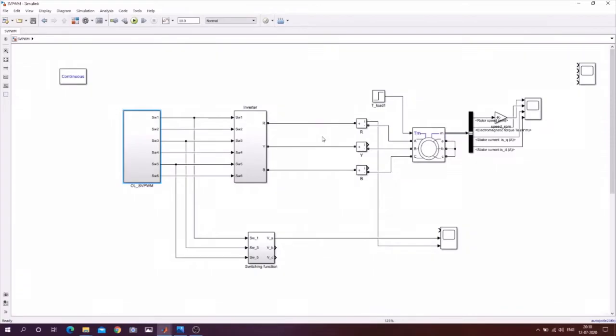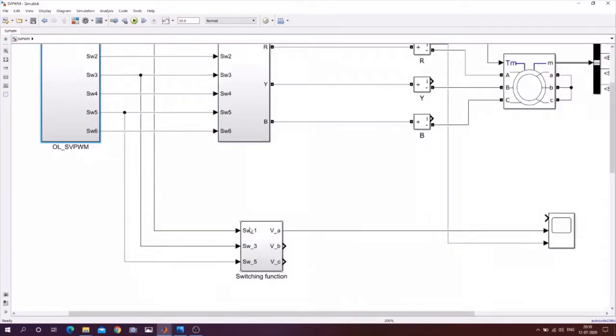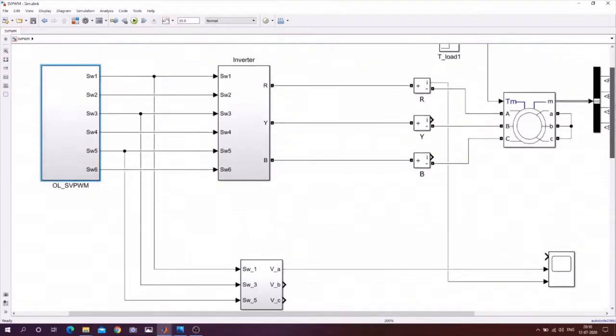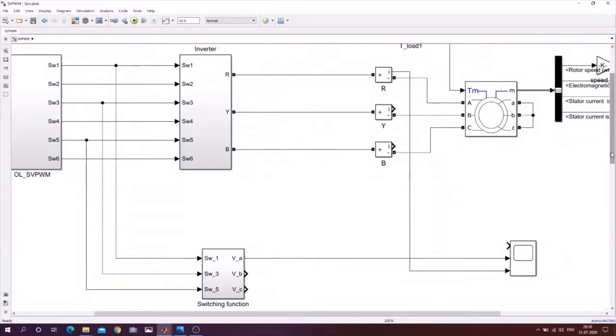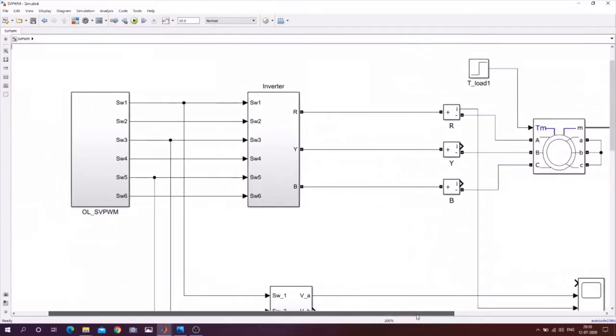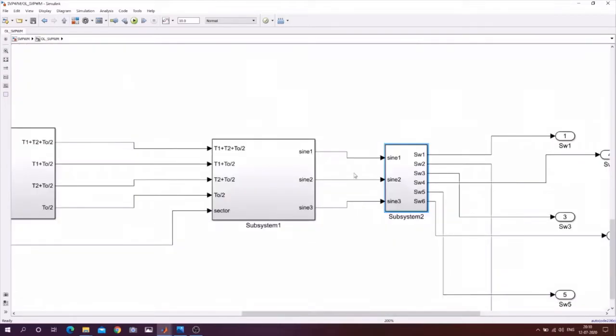Okay, in this section we will see about the SVPWM. So for SVPWM, this is the same switching function from where I have used the switches to formulate the voltage. So I have taken the phase voltage of one phase, the phase current of the same phase, and this one, as I have put previously, the reference wave. Here the reference wave is not a sine wave, but it looks something different. Okay, so let us see how this reference wave looks.